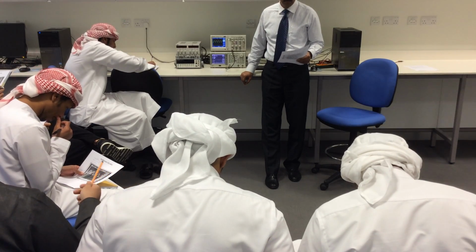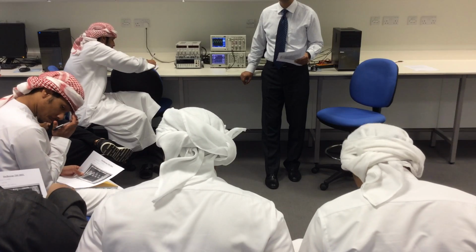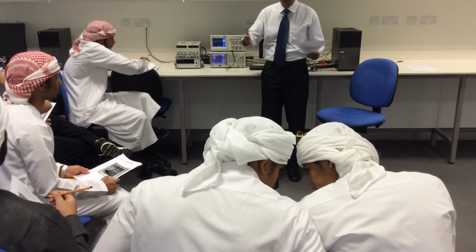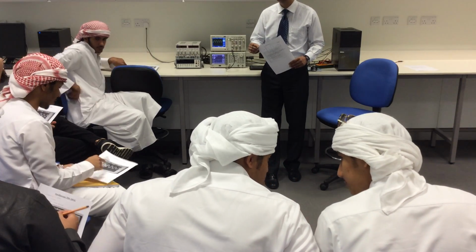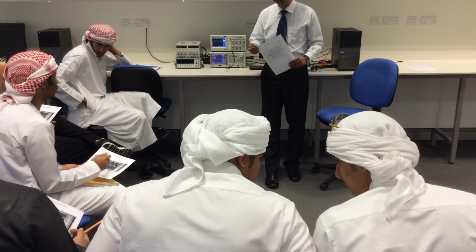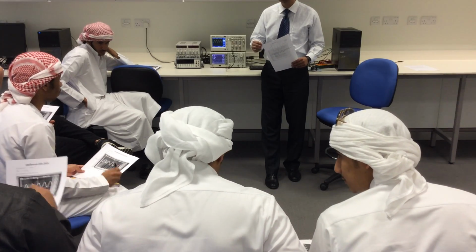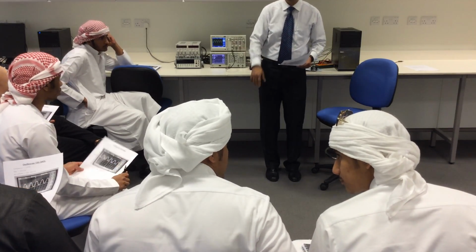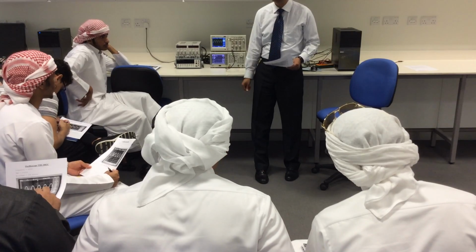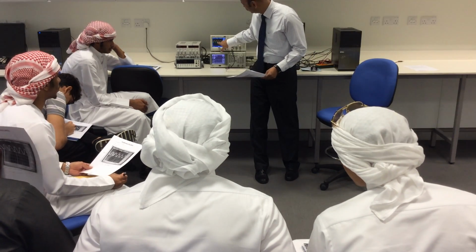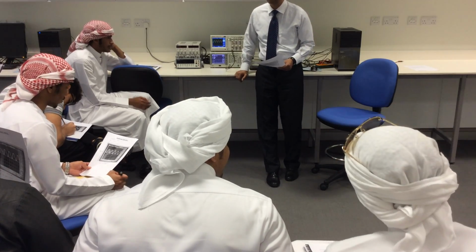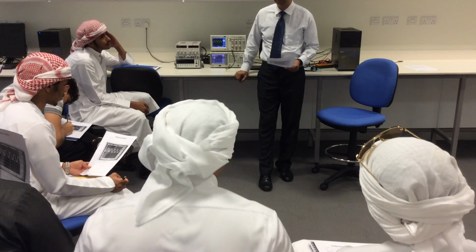Doctor, every time we measure a graph, is each block the same? No. It depends on the VPP and the frequency; it will have a different value. The block is 500 millivolts. Is it always the same with the DC also? No, it is about VPP, it has nothing to do with DC. But using this block, you can find the DC offset. Because you see, your signal from 0 has been moved 1 block up. So that means the DC offset is 500 millivolts.